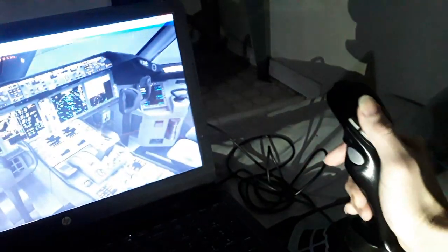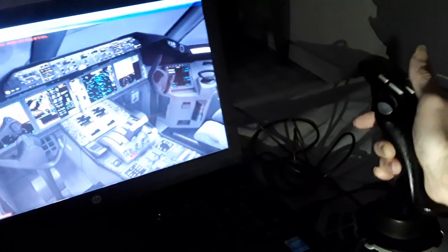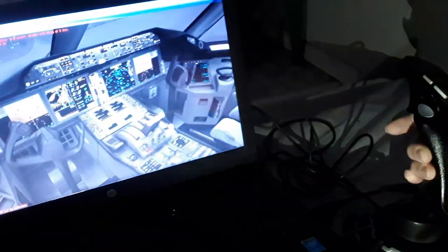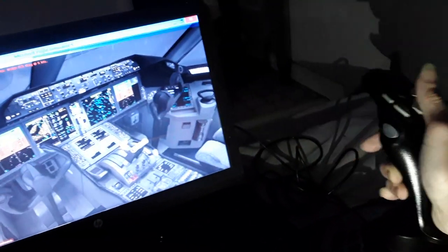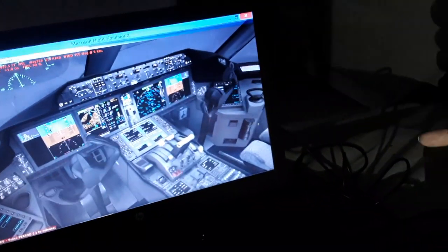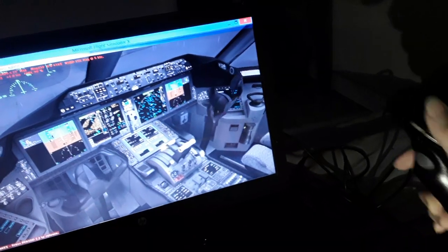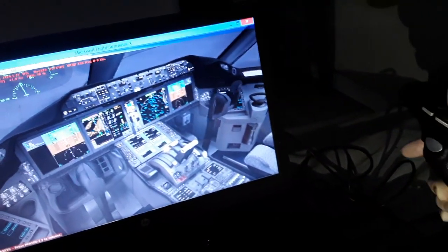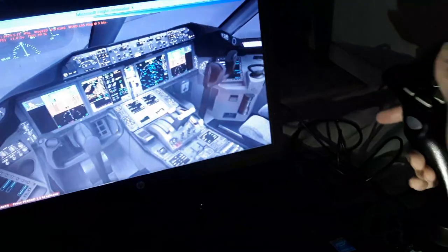So we'll start showing other information from the aircraft, things like the flight controls. You can see we have the side stick here that controls the elevator of the aircraft for climb and descent. As you can see, this is the Airbus side stick, so you can make turns left and right like this. You can use the control wheel in the Boeing aircraft to make left and right turns using the ailerons and the spoilers. This is the pitch axis, the elevator, for making only climb or descent.